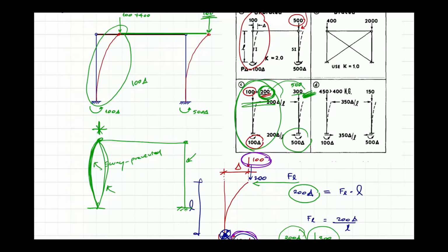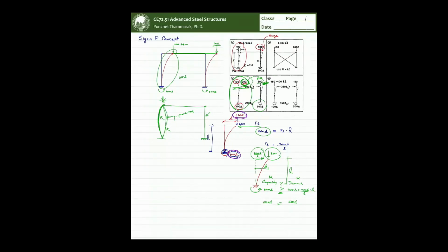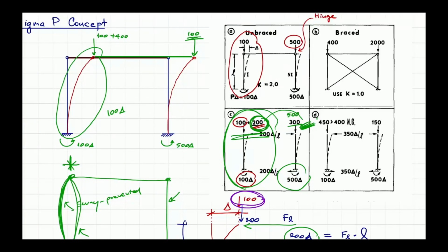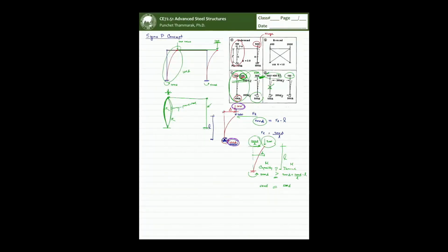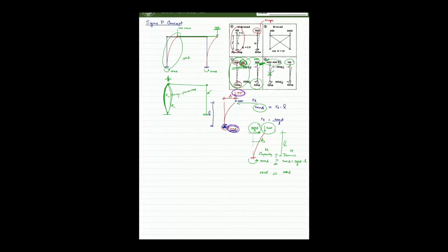Okay. So this is the story. He shows this in the case D. So you see that you put the small load there and add small load on the left side. Even though you have the frame stability against the sway, the individual column fails, it buckles. So you still end up with the failure.